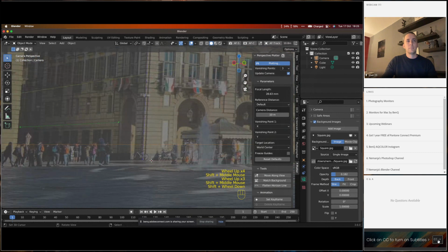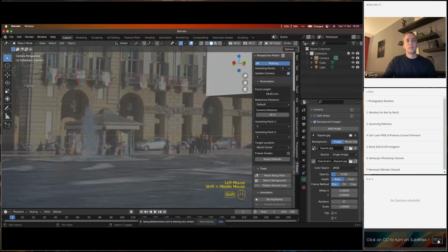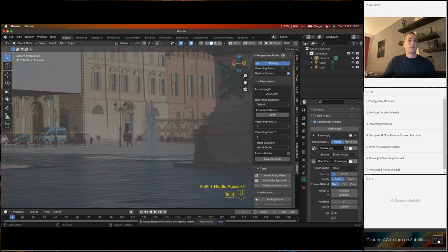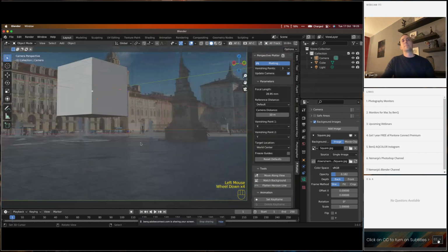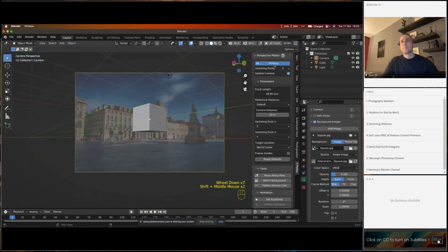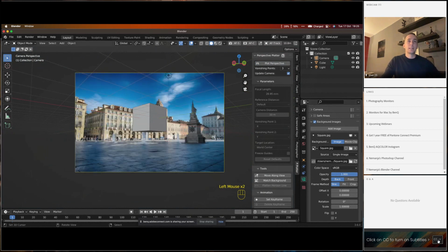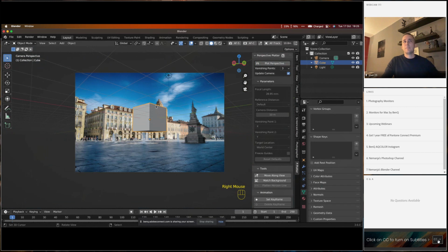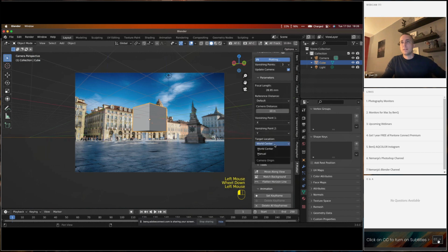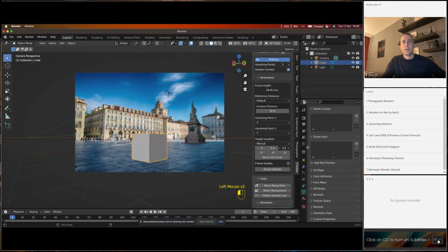And you will see now the bottom of the building. And let's see here, bottom building. And it's pretty cool. If I press here, I'm done. I will go 100% to the image opacity, and this is our cube. It perfectly fits in the perspective, with the difference that the grid of this 3D grid is a little bit up, so we can easily change that by going in here inside, going to the manual, and on the z-axis just putting it up like that.